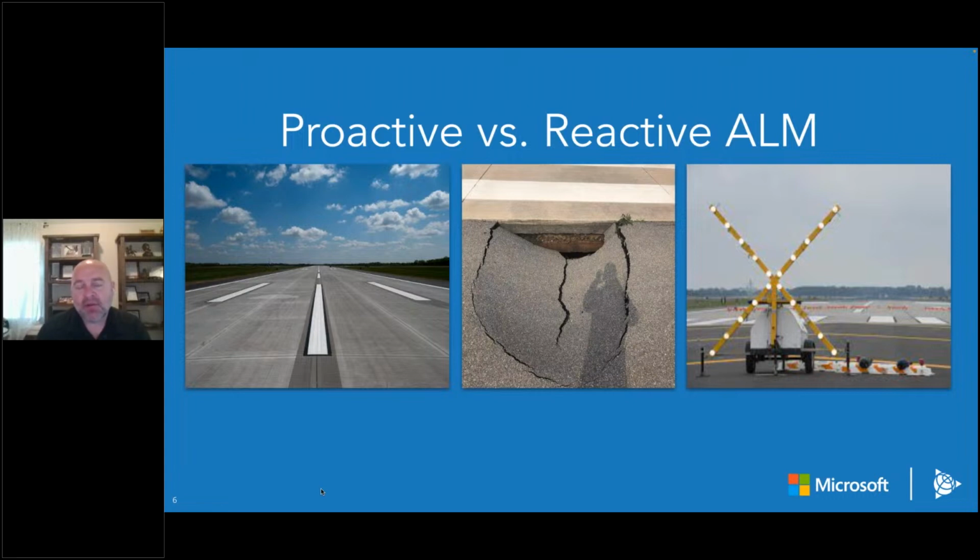That pothole was on the edge of the runway, on our only open runway at the time. And I had our engineers take a deeper look into it, and they discovered a void under the runway due to a failed drainage pipe that was under the runway. And so we had about a 1 foot void under the runway. And I immediately had to shut the runway down, which meant we had no fixed wing operations available to the airfield, which is a big deal.